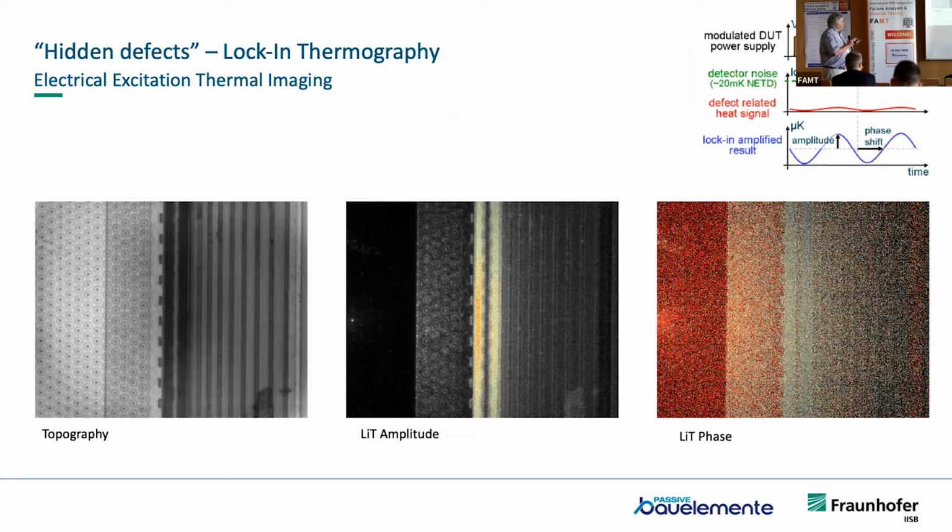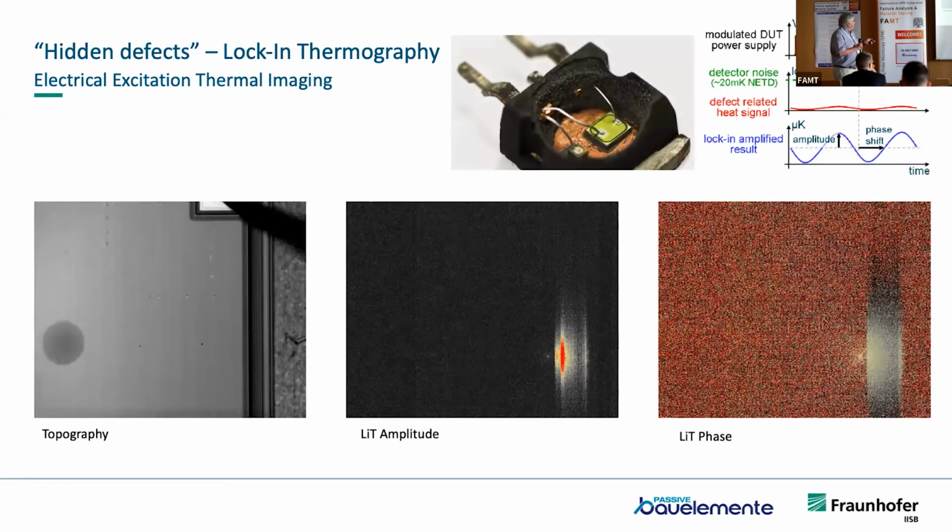Now we drill down and you really see here the gate structures and that it's obviously a problem here at the corner at the guard ring, where the root cause is. And now you can use your FIB and make a picture. If you would have looked at this structure, no way to know where to dig.